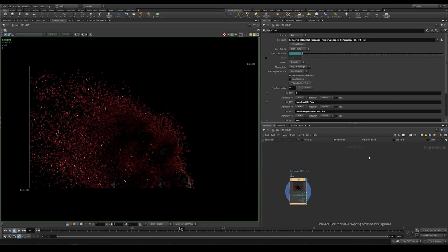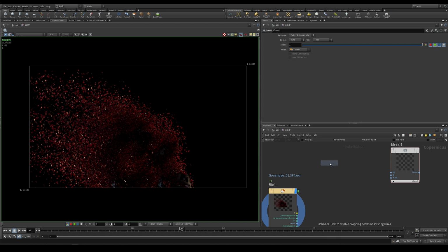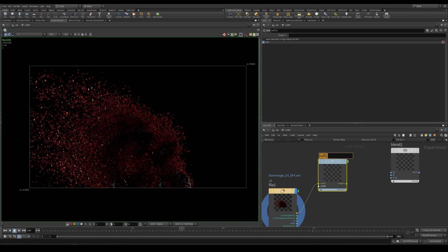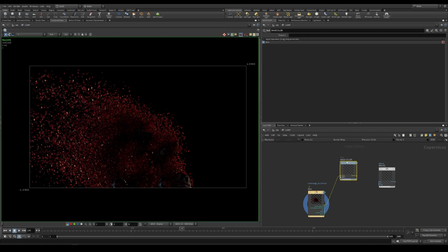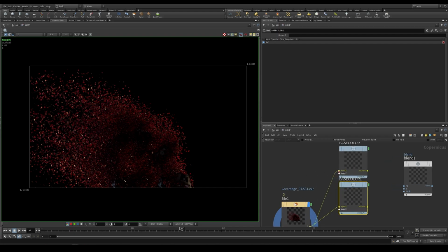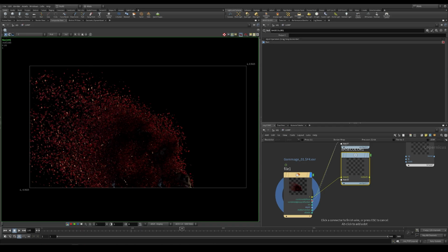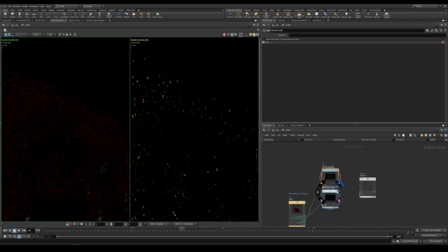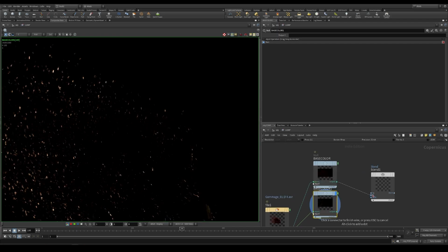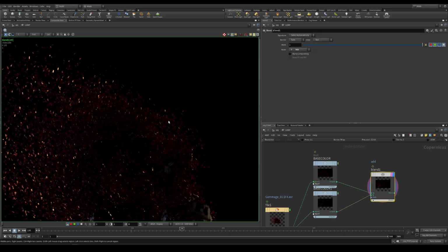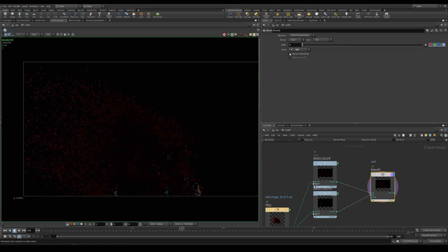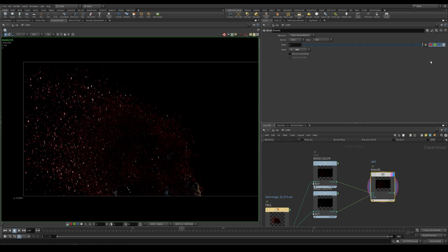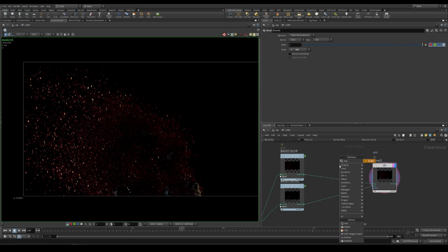Let's take a blend and let's start to take the AOV. So take a null. This will be the base color. And we want to blend it right away. Sorry, not the DC, because this is the beauty pass. We need to take the combined diffuse and blend it with the other pass. So take the glossy reflection for now. So 1 and 2. So we want to blend the base color as a background with this foreground in add mode. So we do have something like this. As you can see, only diffuse. We're introducing the reflection.